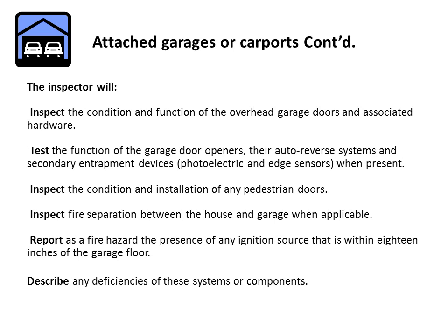This means water heaters and furnaces need to be held up 18 inches from the floor to prevent ignition from sources that are stored within the garage. And the inspector will describe any deficiencies of these systems or components.